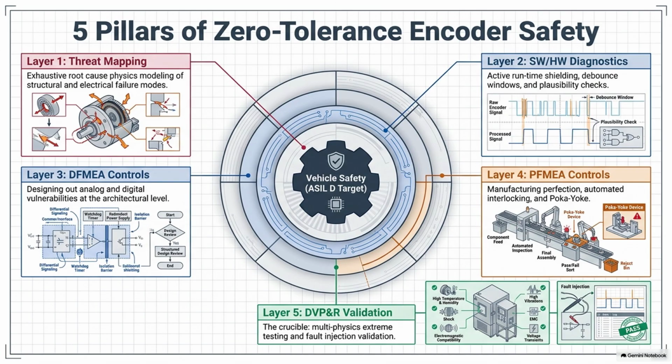So the luminous intensity, the actual brightness of the LED, degrades over time. And the result is this severely distorted pulse amplitude hitting the phototransistor. The receiving sensor isn't getting a clean on or off signal anymore. It's just getting a weak wave. Exactly, a weak erratic wave. And this leads to what the engineers call pulse loss or phase distortion.